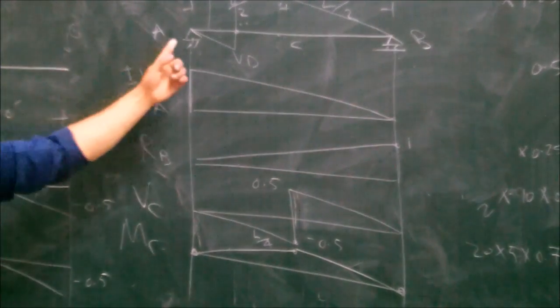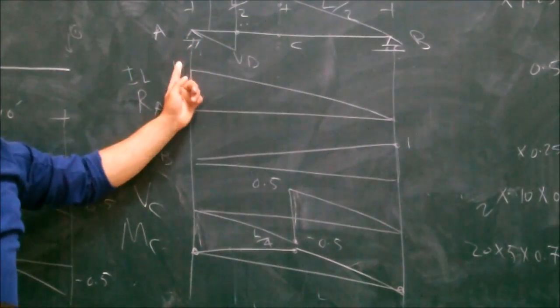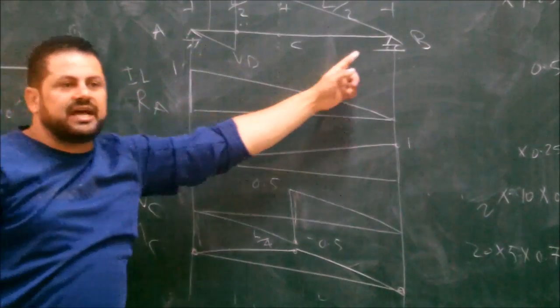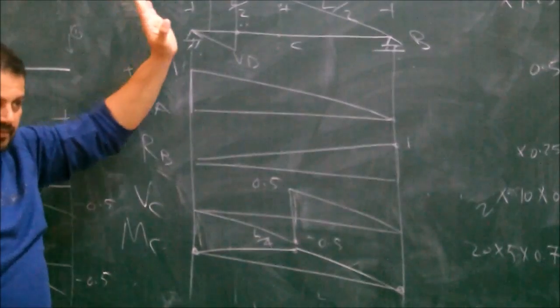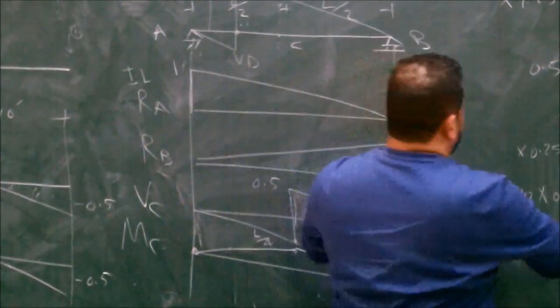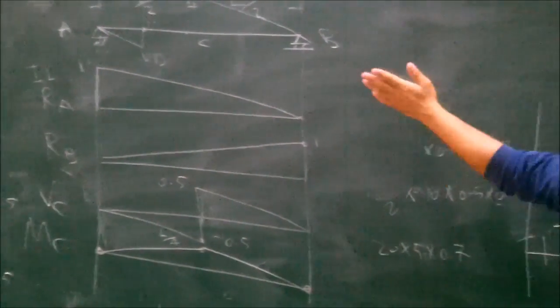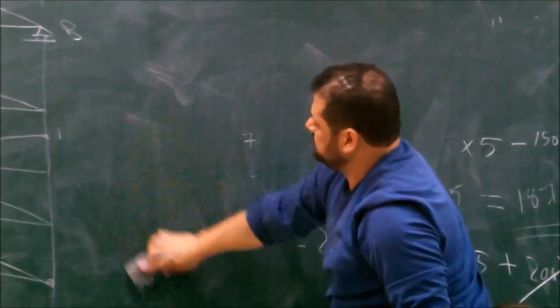What's the shear at A? The same as the reaction at A. What's the shear at B? Minus the reaction at B. Done? And for any loading, you place the load to maximize.